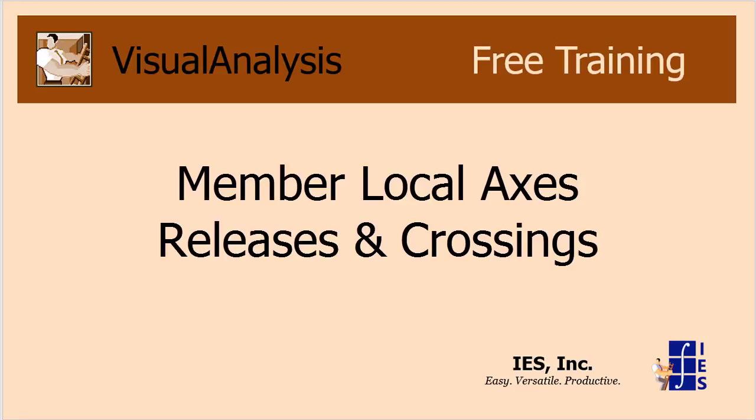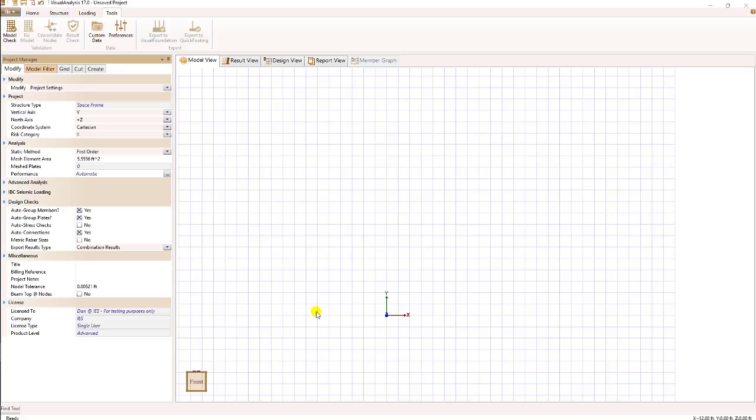In this demonstration, we're going to talk about member local axes, member releases, and member crossings. You might ask, why do we need to talk about member local axes? The reason is there are several things that are tied to the member local axis coordinate system, and it's important to understand how it's defined. Those things include releasing members, loads on members, end effects on the member, and lastly, certain results.